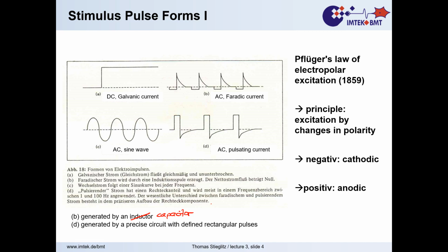So we switch on a current. First part on B. We switch off the current, and when the current passes a capacitor, the amount of charge that the current gives is stored on the capacitor. And if we have a reasonable amount of switches, we can then decharge the capacitor. And if we wait long enough, the current that goes from the capacitor is the same current that we put on the capacitor before. So we have an analog charge balance between one phase and the other phase.